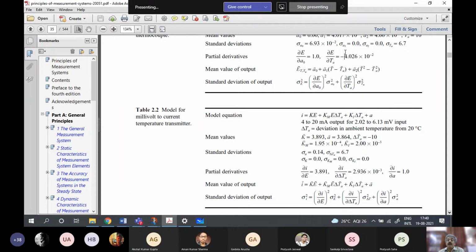Probably, because these values seem to be well chosen. Anyway, whatever it is, 4 to 20 milliampere is a very standard range. The standard current transmission range is 4 to 20 milliampere. Every current converter, every current transmitter will have its output in this range.